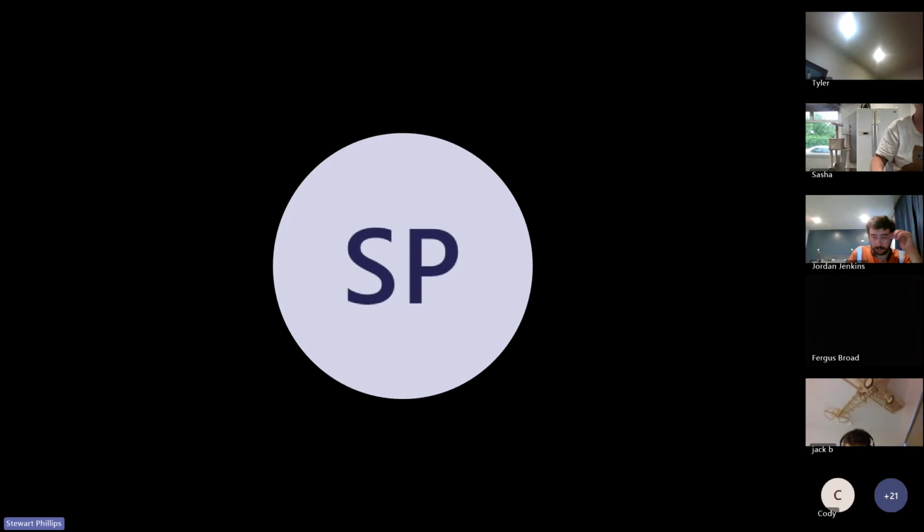Well, yeah, Daniel basically hit it on the head. So an overload relay primarily protects motors by responding to prolonged overloads and preventing overheating, because it takes time for the bimetal to heat up and then trip the circuit. Whereas circuit breakers provide broader protection, including overload and short circuit scenarios, and can isolate circuits quickly.